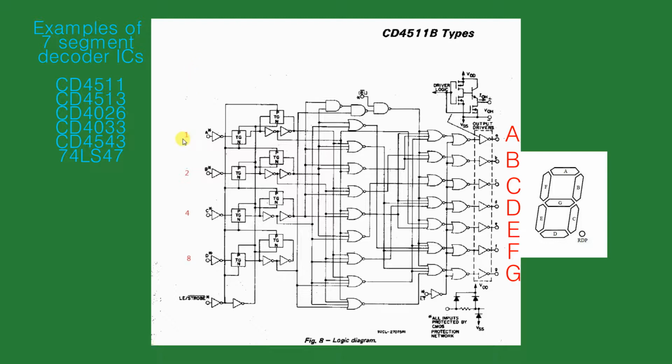All we have to know is that if we put our binary 1 through 8 here, that's all we need to provide 0 to 9, which is what each display can handle. So if we stack 2 displays together, we can go up to 99, or 3, we can go up to 999. What happens here is when you put a high on the 1 pin, that is converted to the correct segment high on this pin here.